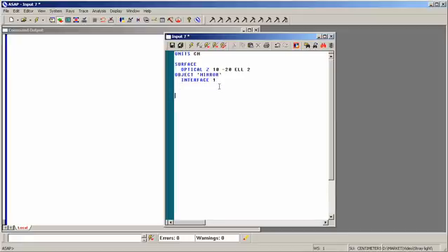Now we have to define a collimated source. Grid, elliptic, we'll place the source at z equals 0, give it a semi-diameter of 1, so we're going from -1 to 1 in x, -1 to 1 in y, and just for an example, we'll have a 25 by 25 grid of rays. We're going parallel to the z-axis, source direction, x component of 0, y component of 0, z component of 1. We're going to set up a window in the usual way. A rectangular window with the vertical axis being y and the horizontal axis being z. Profile, overlay, trace, plot.